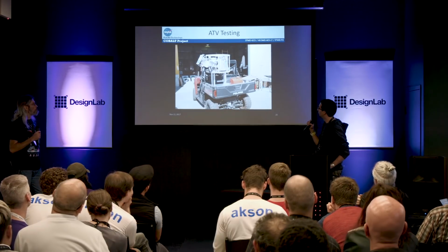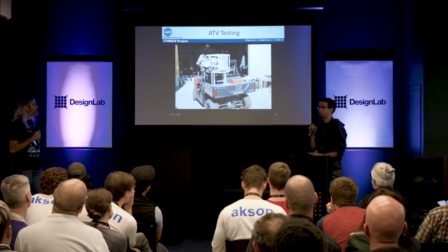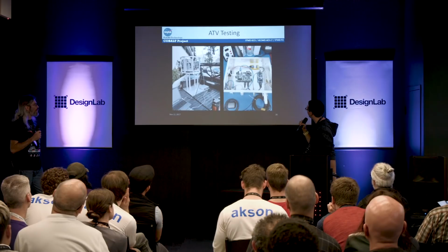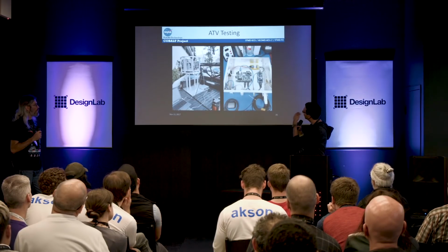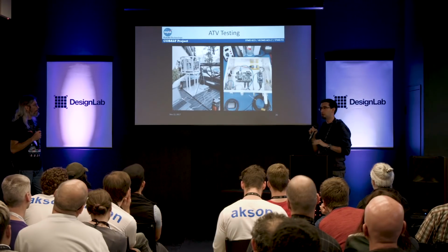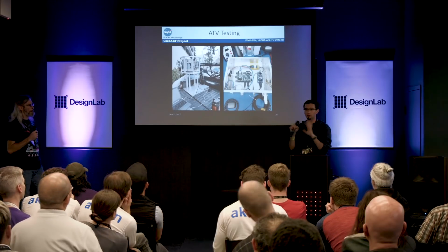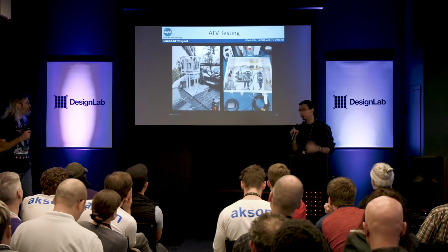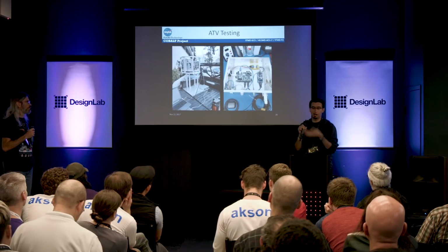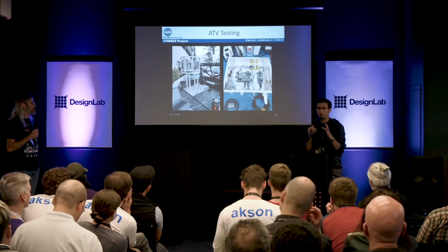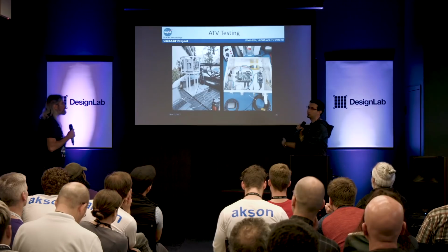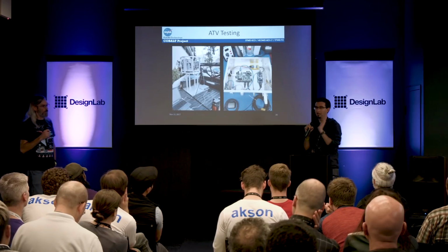back at home. So we put the payload on a Polaris that was actually left over from our DARPA Robotics Challenge, bolted it on, built a little box using some Digilent parts, like a Zynq processor. It's a nice little ARM FPGA board to simulate the same exact timing and voltage characteristics as the rocket. So this box pretends to be the rocket, and as far as Cobalt knows, it's moving. The IMU and the LiDAR are seeing data being excited, and it's talking to a box that looks to it exactly like the vehicle.